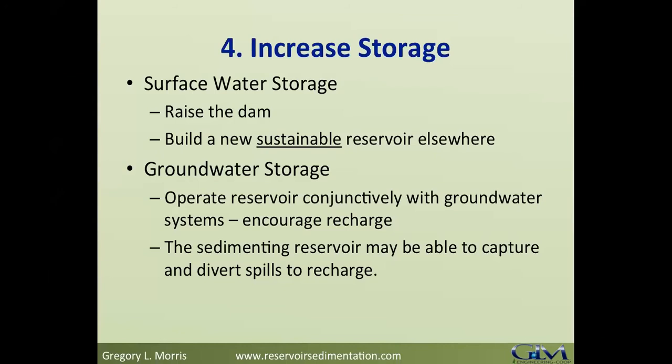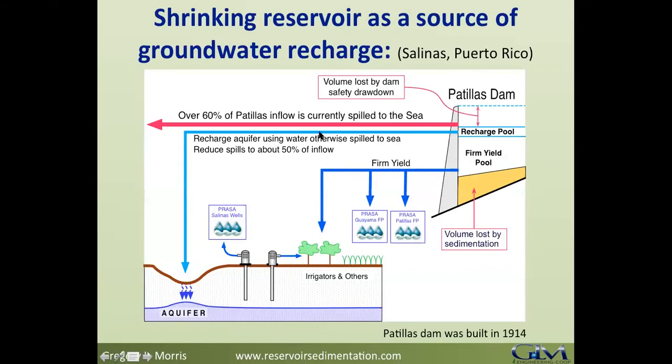Groundwater, of course, has the advantage of not being subject to sedimentation, and by operating a reservoir conjunctively with groundwater systems, you can generate a lot of benefits. Encourage recharge of groundwater systems, and the sedimenting reservoir may itself be able to capture and divert spills to recharge. For instance, we have a project we're doing like this in Puerto Rico right now.